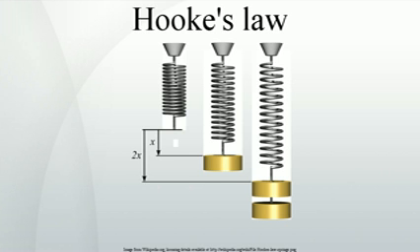The stiffness tensor, on the other hand, is a property of the material, and often depends on physical state variables such as temperature, pressure, and microstructure. Due to the inherent symmetries of the stress and strain tensors, only 21 elastic coefficients of the latter are independent. For isotropic media, which have the same physical properties in any direction, the stiffness can be reduced to only two independent numbers, the bulk modulus and the shear modulus, that quantify the material's resistance to changes in volume and to shearing deformations, respectively.